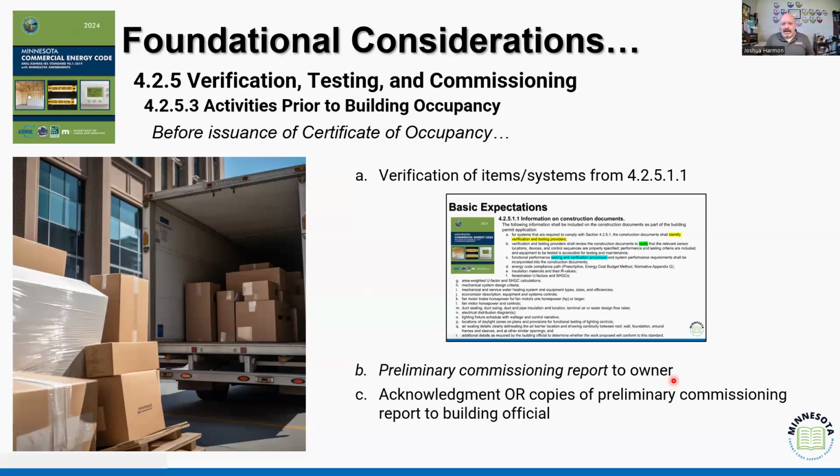So when the battery died, guess what? I didn't have control anymore over the system. The system was still capable of doing what it needed to do, but the control needed to be verified. And so I had to go and verify, and I ended up finding out that they just didn't wire it properly. There was a loose connection. And so that's why I wasn't getting direct power. So again, these are the kind of things that are going to be identified as part of that process.